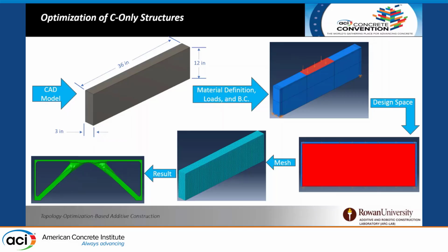For this specific example, you can see that I added a uniform load in the middle third of the beam, and that's because I wanted to force the software to make a single arch structure, even though the members are straight, but that's because Abaqus mostly deals with steel, so it's not used to simulating for concrete.